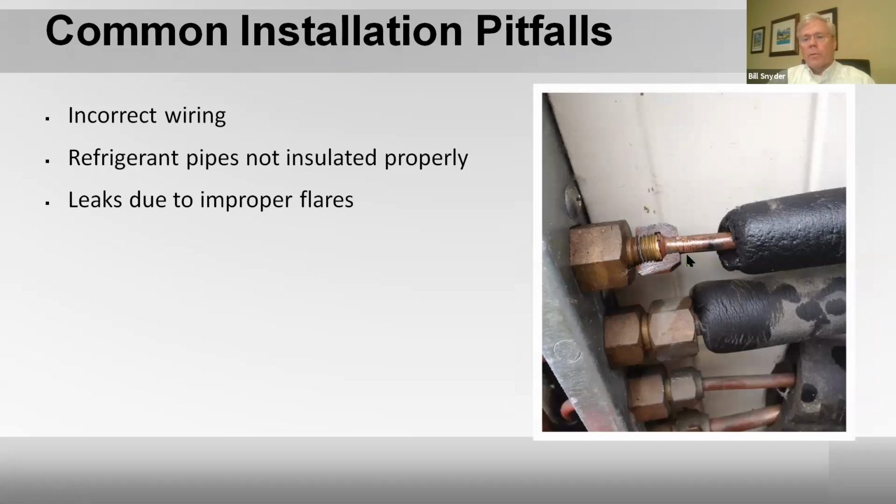Leaks due to improper flares. This flare is actually cut in half, so you can kind of see what the flare looks like. But what they're showing here is some oil. If you ever see oil around a fitting, then you probably got a leak, because a little bit of refrigerant oil will leak out with the refrigerant itself and typically will leave a stain of some sort. That's a good way to find your leaks.